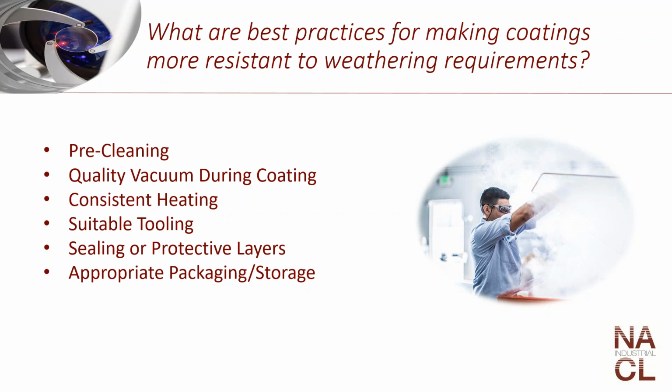A lot of coating vendors now are also working with sealing or protective layers, hydrophobic films, that sort of thing. So this is a monolayer that will go on over your dielectric film and, for lack of a better term, seal the film in. If it seals the film in, it's hydrophobic, so humidity, moisture, salt fog, that sort of thing will roll off the lens. You can think of this as like a permanent Rain-X that goes on a windshield, but it never needs to be reapplied.